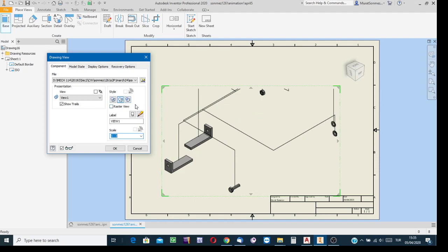Well, click on this intermediate button because it is not a detailed drawing. It's an assembly drawing. You know, in assembly drawings, we omit the images of hidden entities. So this style is OK. To be able to have the components in the color of the material or in the color they have been painted, as if you see those in the solid model environment, click on this style button as well.